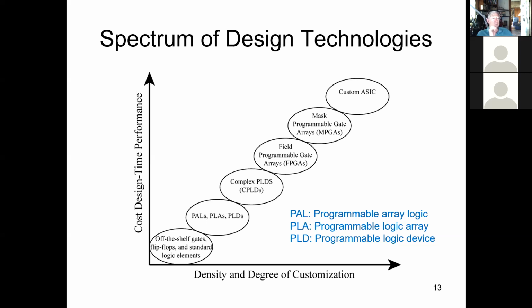So this is kind of like a custom FPGA, if you will, but there are two big advantages. One, remember an FPGA uses a lot of its silicon real estate for its programming nature. Whereas if you do this programming with a mask, then you don't have the significantly larger amounts of real estate used up by conferring the ability to make this a programmable device.